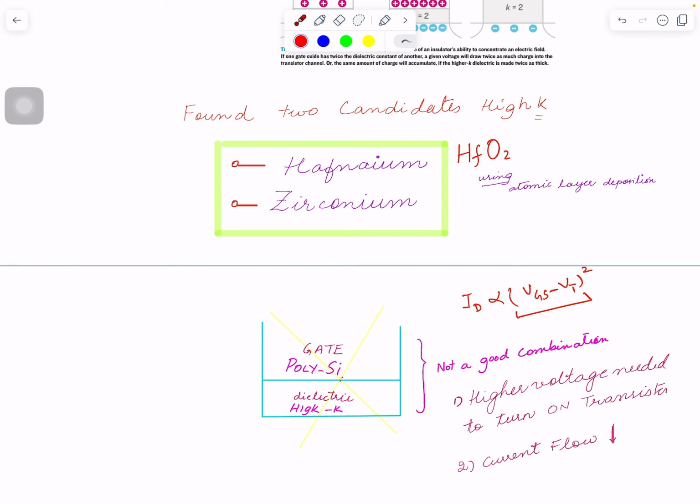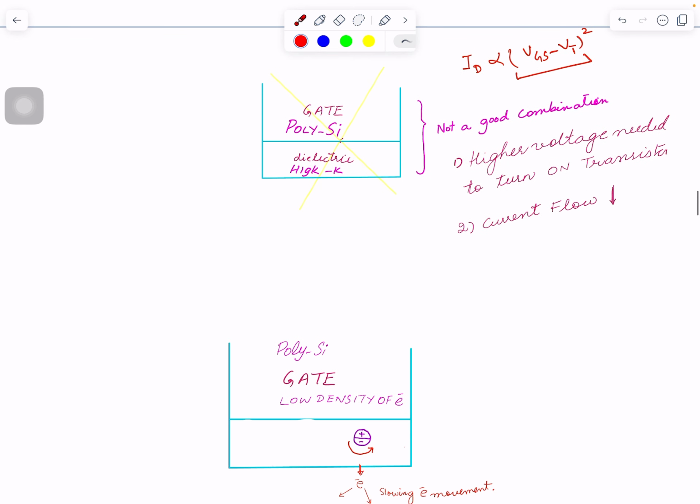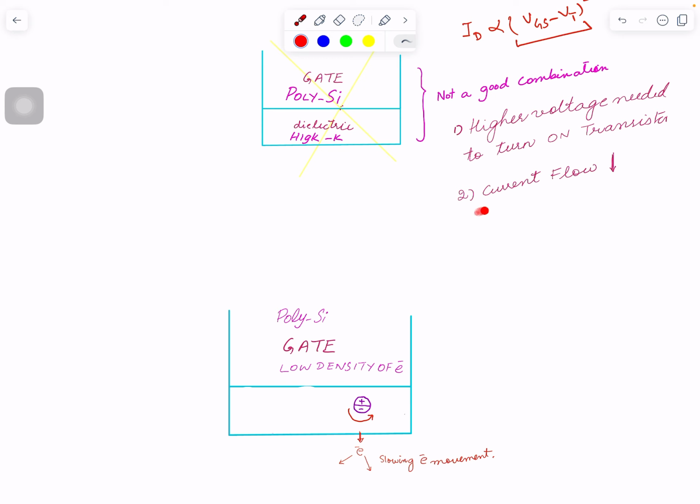Another problem: not only because of that, but even for the same threshold, current is much lower with this type of combination. The reason for that was the second thing that I mentioned here. It's written in the paper too that we have these objects with charges in the form of a dipole. So there's a positive charge here and a negative here. This orientation is an important factor for the material to be high-K, because it has this dipole type of structure.